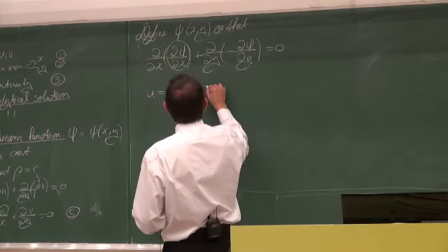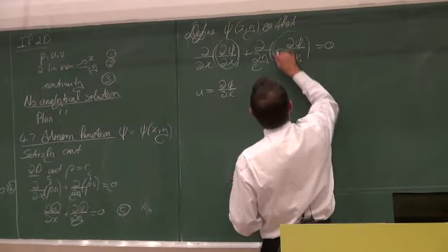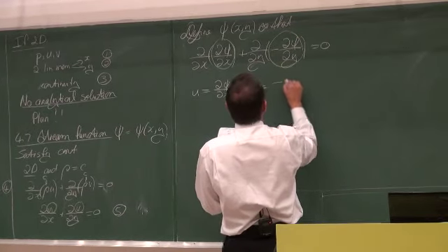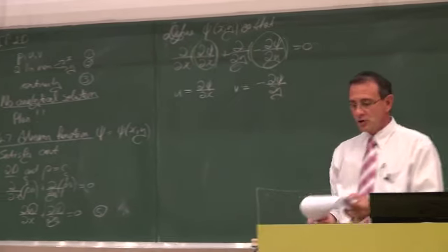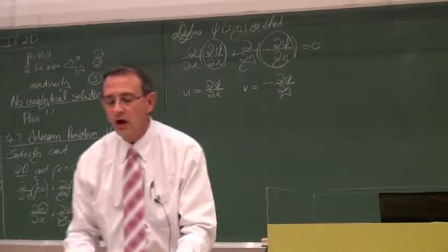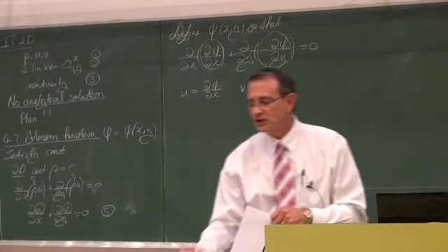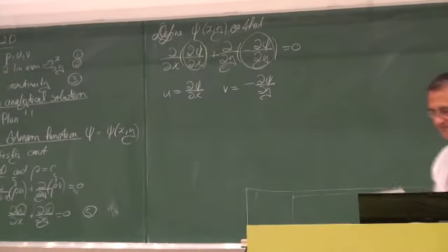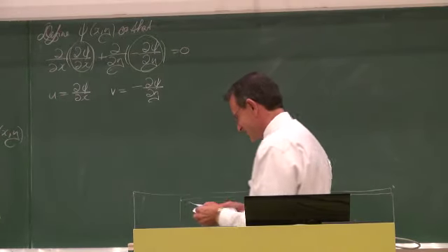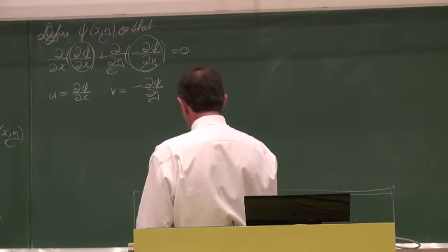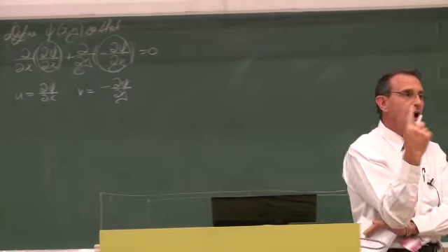And this v term, if we look at that one there, and that one there, v is equal to minus partial psi dy. Why those two? Well, people tried a long time and they found that these two work. So it was by trial and error. So it is sort of a mathematical trick for replacing the two variables u and v with one function, psi.